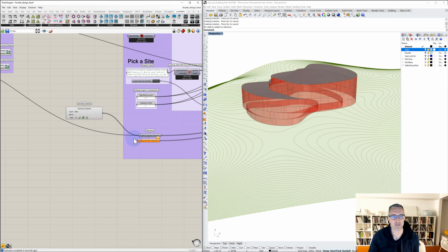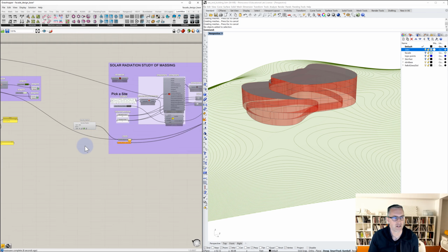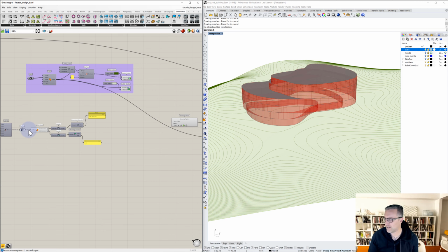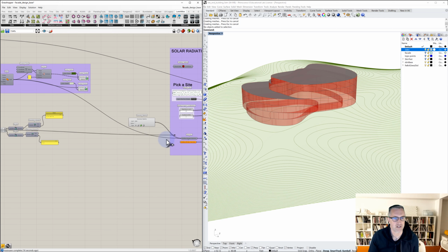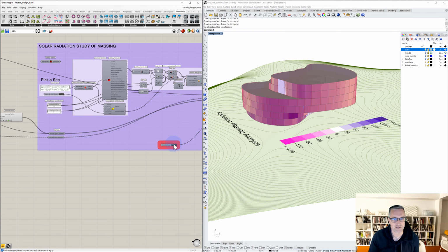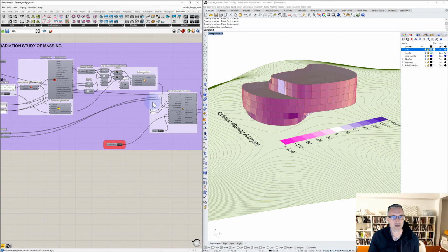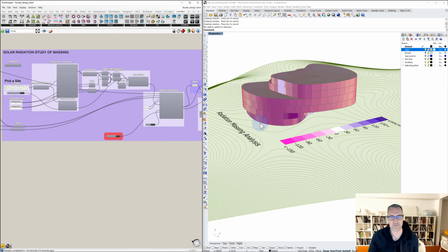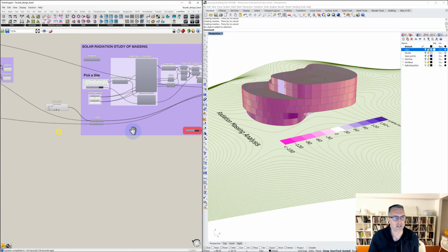And then we want building window geometry. And so this is going to be our surfaces that we just created. And let's pull in the surfaces. So that worked already. And if your computer's a little slower as you're doing other things, we may want to change the boolean toggle for the radiation analysis. So let's take a quick look at this and see what's happening.